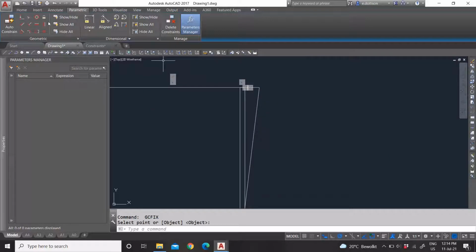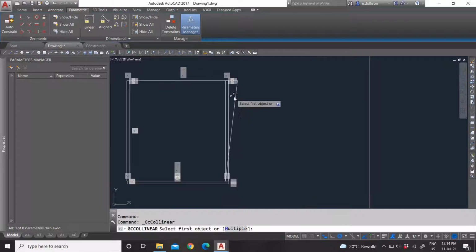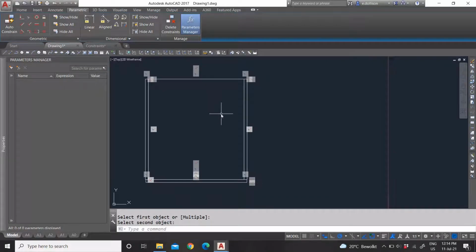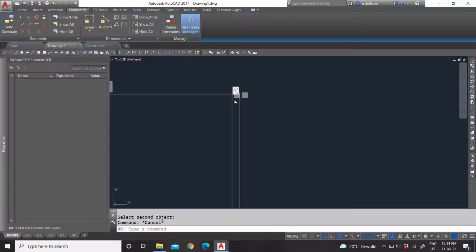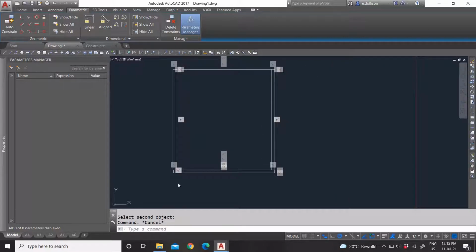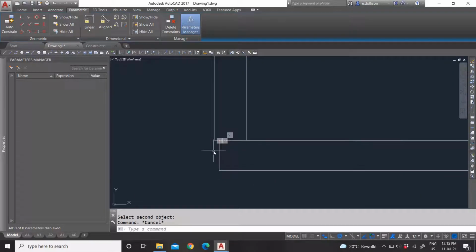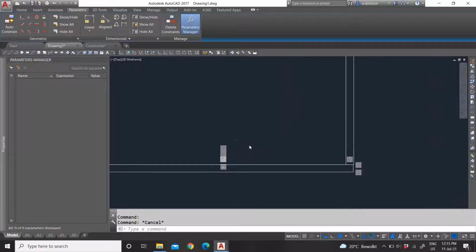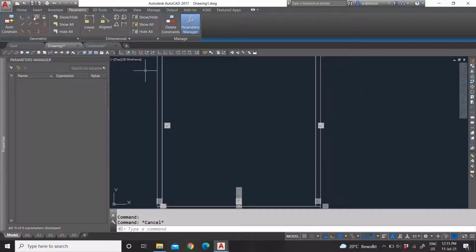So you also have to think about how it will respond to your parametrics. So as you see, I used the collinear again, and instead of it going at an angle, it just came back in this direction, meaning straight. That is because I locked these two corners right here. So that is also handy to use. So now we had this one and this one.